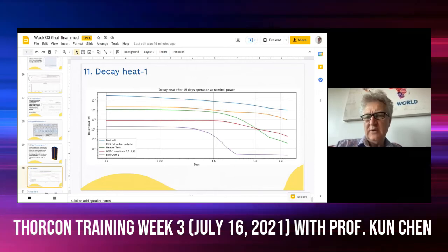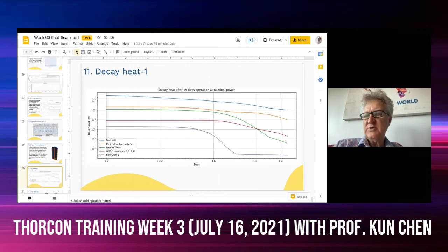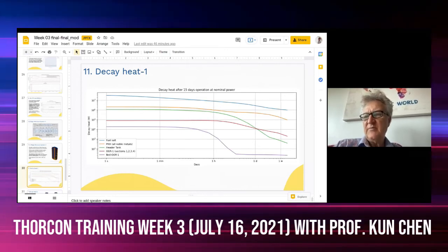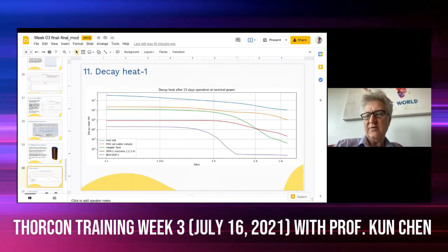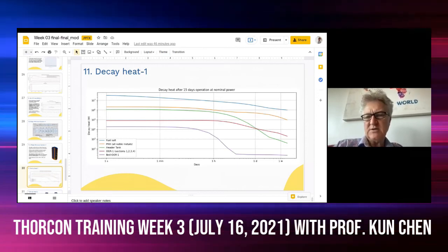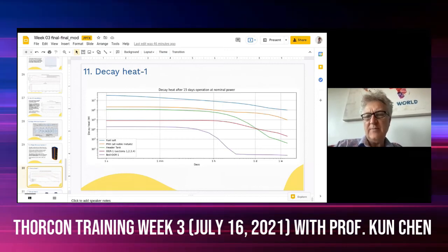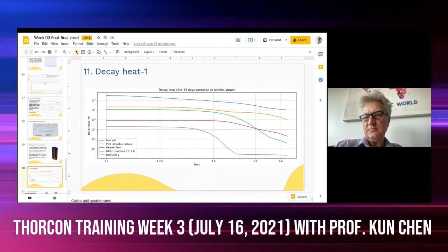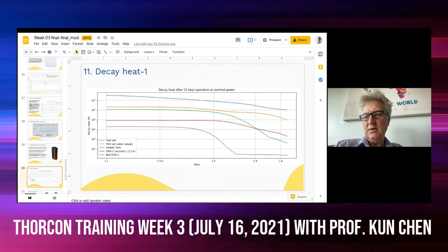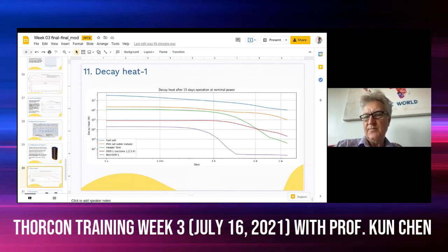Not a whole lot, but a little bit. So we will have to adjust the temperatures, but otherwise they're going to be very similar. We will have to build a freeze valve and do component tests on it to find the right temperature settings. But otherwise, I think it's going to be basically the same.